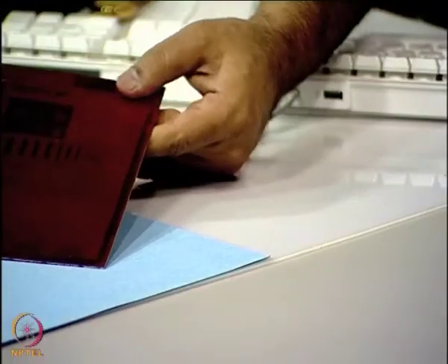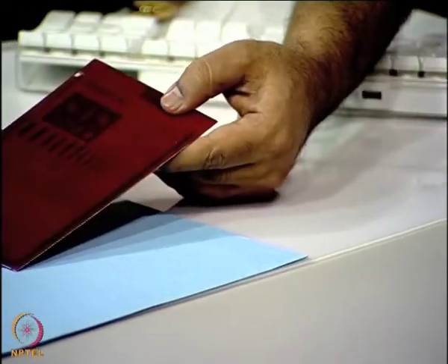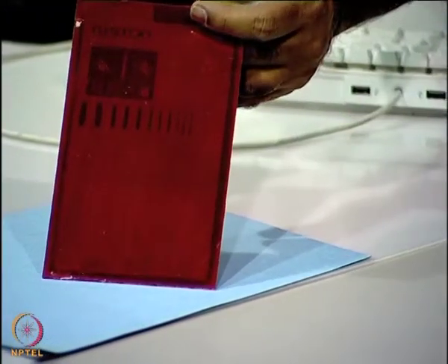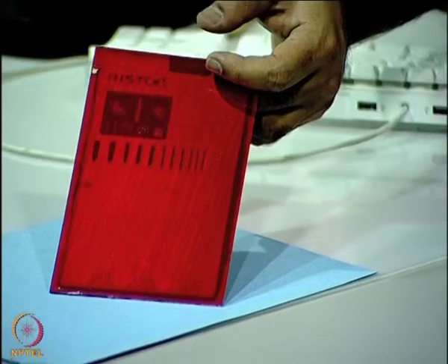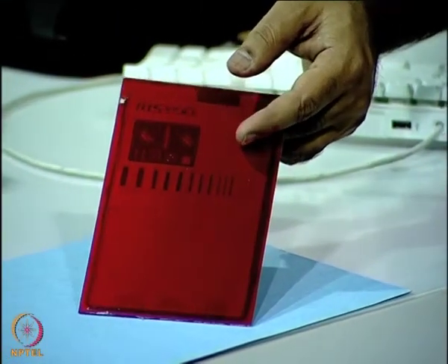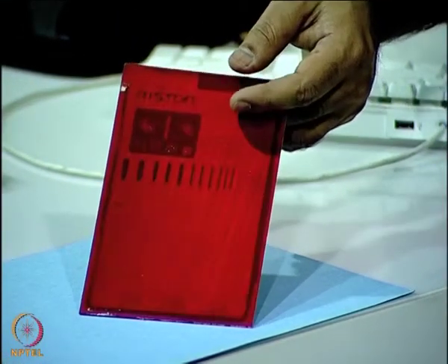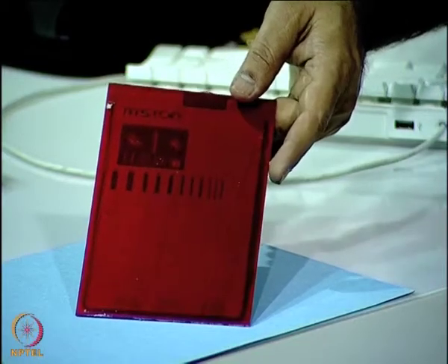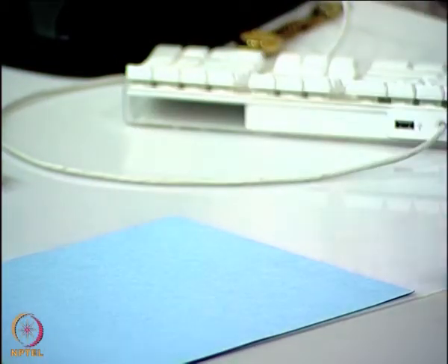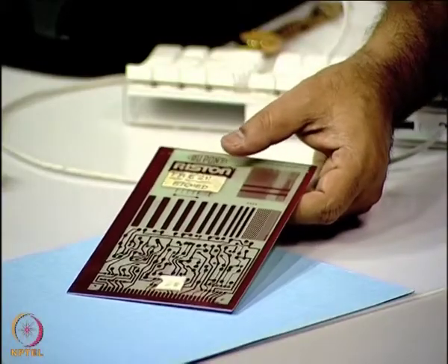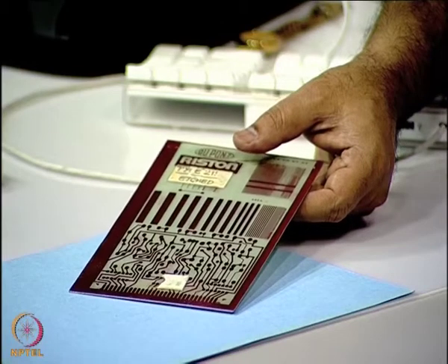I will also show you some of the samples that have come out through those processes. You can see here, this is a photoresist coated copper clad laminate. The red material, dry film, that you see here is a photoresist material. Now, this is imaged, as you know, and then it is developed. So, you can see here, after the photoresist